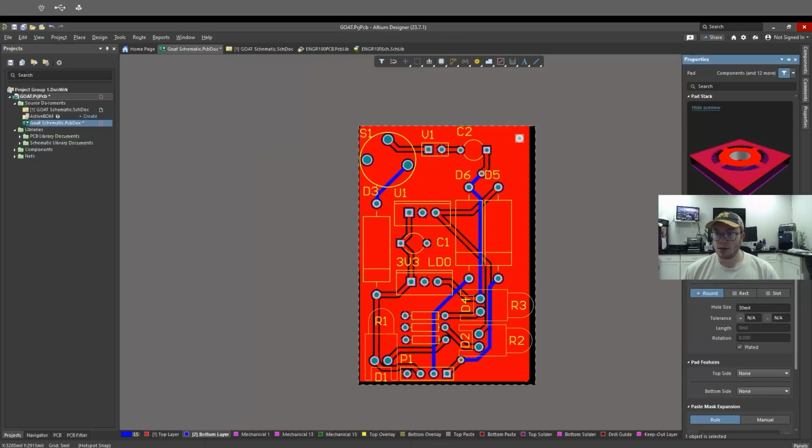and I'd like this to be, let's say, I want it to be a 2 millimeter mounting hole. So I know, just off the top of my head, you don't need to know this, I know that 2 millimeters is about 80 mil. So we want the size of the ring around it to be 120 mil. And then we're going to make this 80 mil.